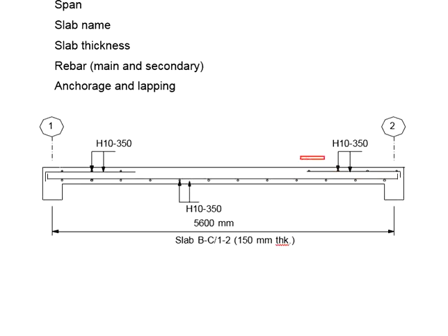Now, when you provide the top reinforcement here, you cannot simply indicate it's stopping somewhere without giving any dimension. Under such circumstances, the contractor does not have any idea where to stop this reinforcement and where to stop the reinforcement here. Now the question here is, how do you determine this distance?